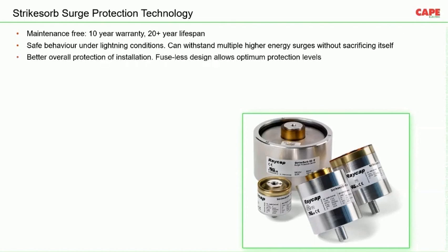Better overall protection. Fuseless design allows optimum protection level. Up to certain ampere rating, these SPDs don't need a backup protection. So that will allow a very less voltage protection level. Suitable for direct installation with high surge current. For the places where these surges are very common and very frequent, we can use these SPDs.